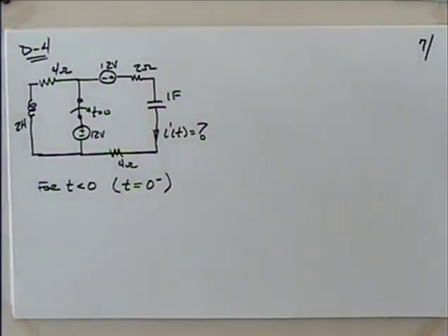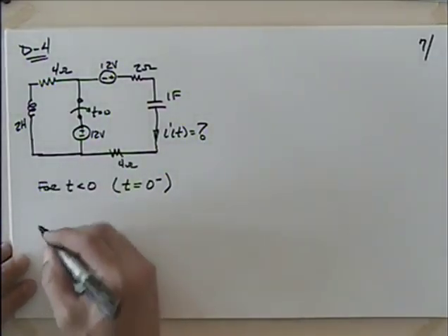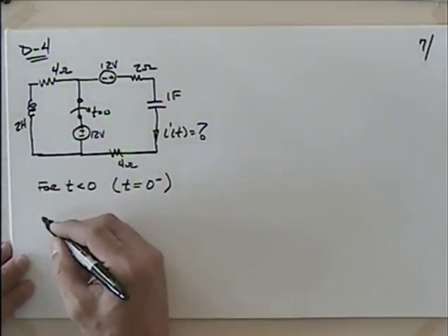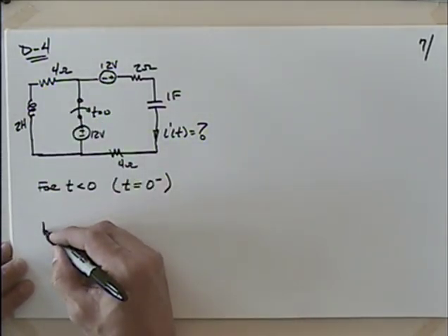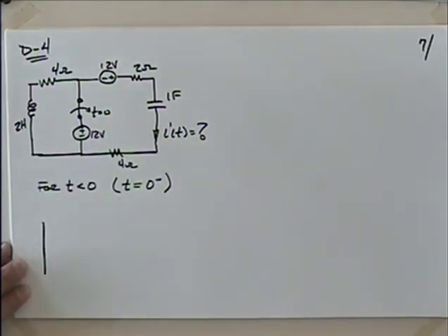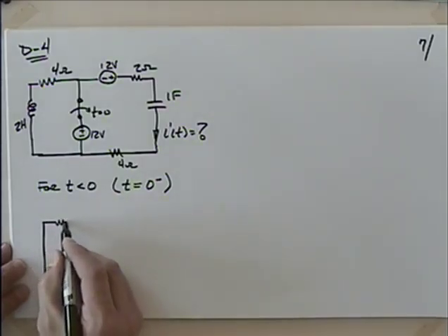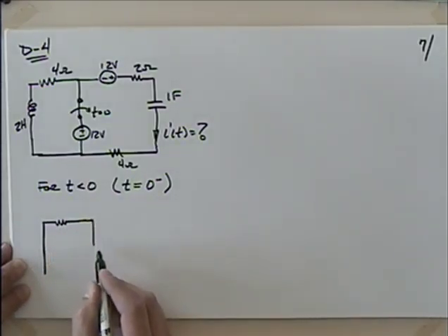Okay, so the switch is still closed. What's this thing going to look like? Well, what do inductors look like to a circuit that's been sitting for a while? Yeah, a short, because our inductor has 0 resistance, right? So we've got a wire here. The switch has been closed for so long we don't even know it's a switch.